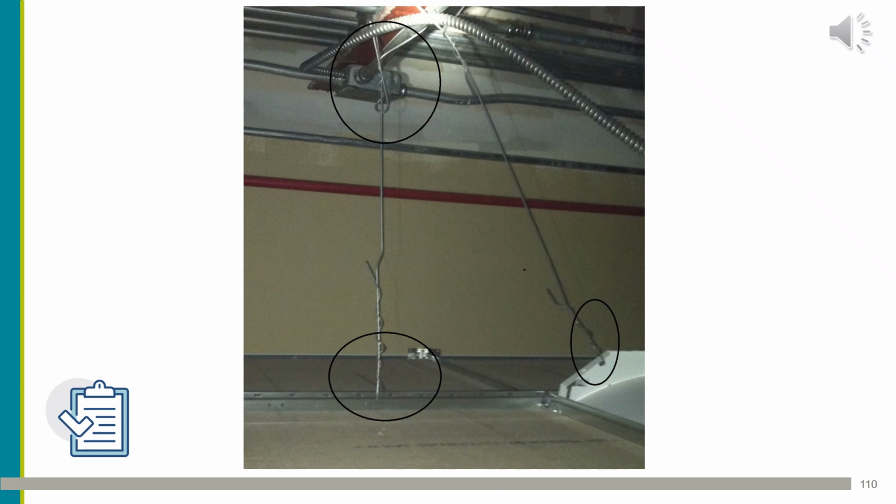What's interesting about this one is 2 or 3 different things. First, on the lower part at the grid, at the T where you see the wire, we just have the wire kind of meandering up, and we also have the clips bent to try to adjust and level the grid, but we obviously do not have tight attachment and 3 tight wraps in 3 inches on the lower. Same situation to the immediate right where it's attached to the light fixture. Now if you look up to the structure, what you'll see interesting here is they made a loop that went all the way around the structure, and it also included a conduit. So this is a fail by every respect.